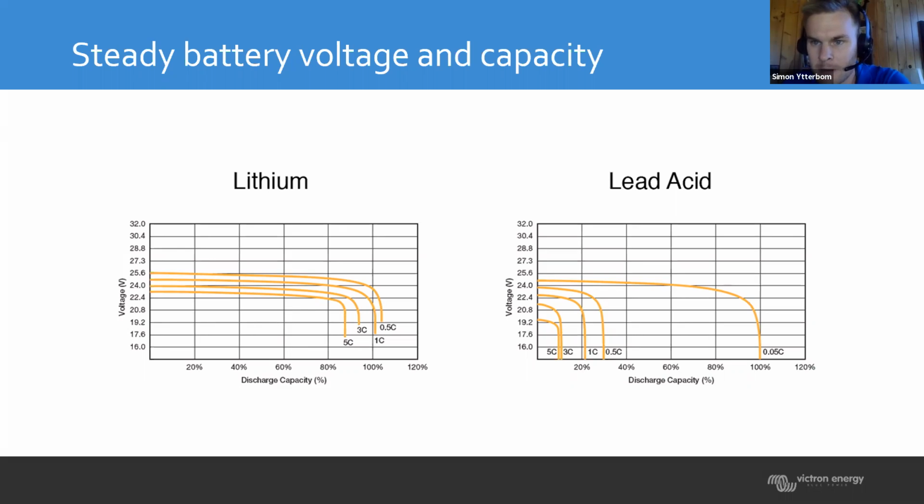So this 100 amp hour battery, under these circumstances, is now only worth about 40 amps. Factor in that we only want to use half of its capacity, and that 100 amp hour is 20 amp hours under these loads. So lead batteries are not suited for high discharge rates.